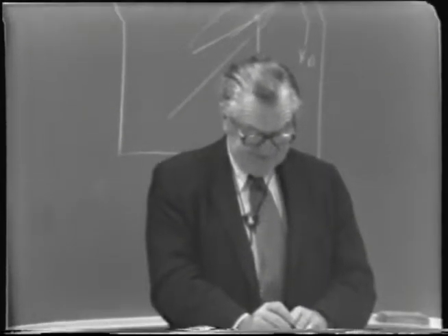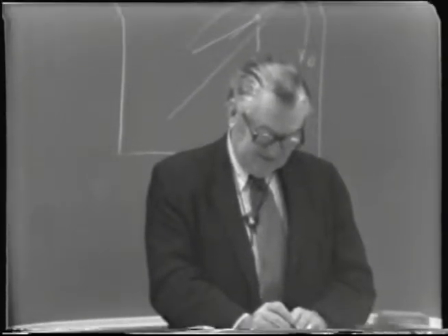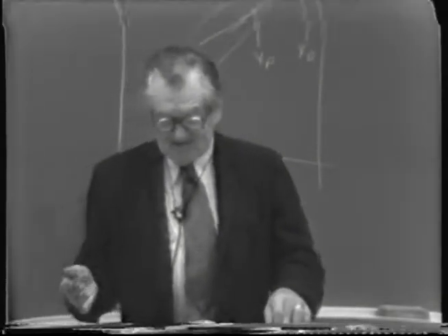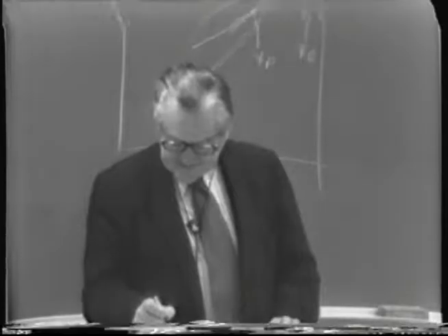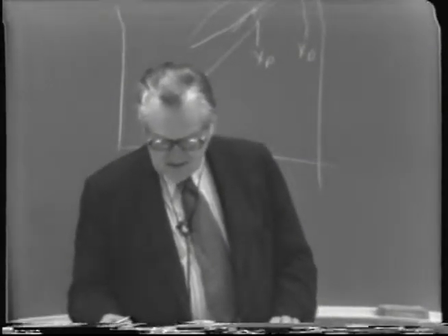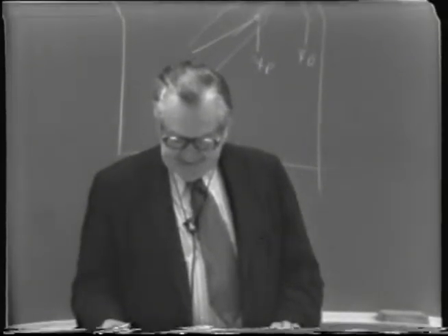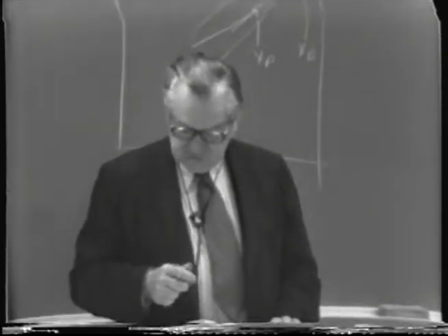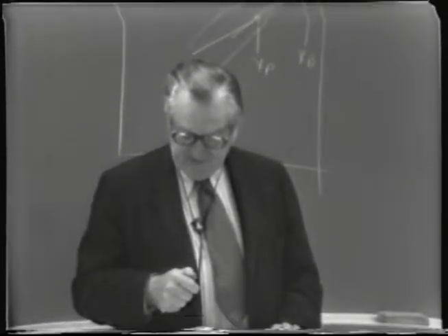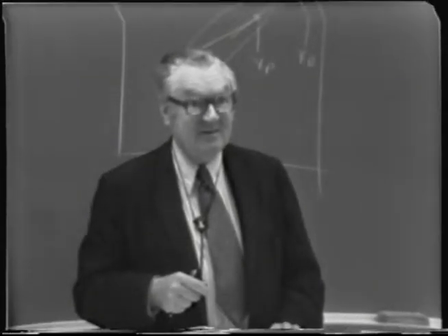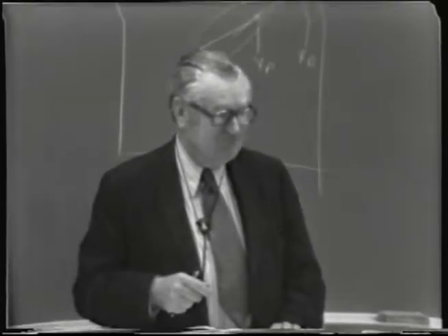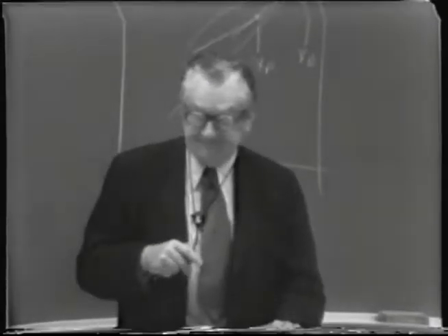And so if we had some plate efficiency factor to apply, which we have stated here as 0.8, well, I didn't work that out, but let's say if you wanted to say 11.5 divided by 0.8, how much would that be? About the 14th tray or something like that.